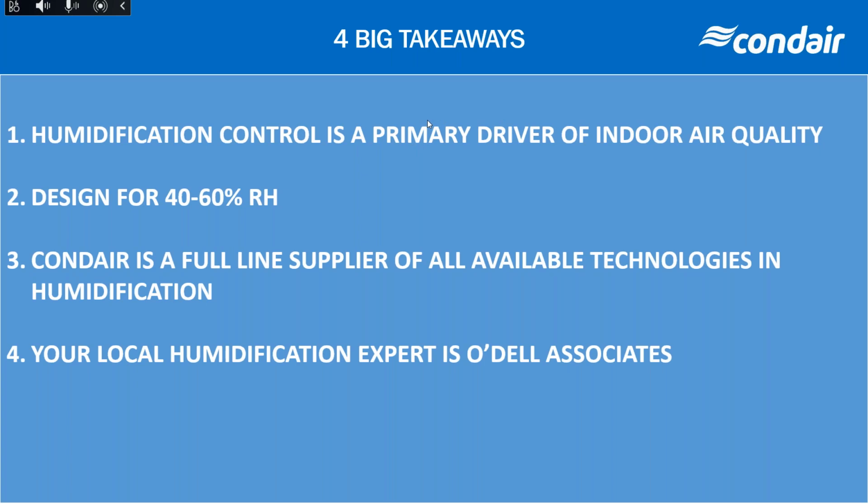Typically in Ontario, if you don't humidify, humidity levels in a residence would be anywhere from 15 to 20% in the middle of winter, and that's with people showering and bathing regularly. That's more anecdotal. I don't have any studies, but I've been in enough houses and provided humidification to enough residential spaces that those are the numbers we see at the start.